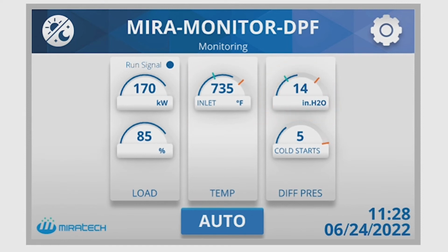You may have noticed a delay between when the parameter was outside the acceptable range and when the alarm was triggered. Those are fully customizable within the alarm set points menu to allow users to fine-tune exactly how fast they want the alarms to be reported. In some cases, you may want a long delay on low temperature, but a very short delay on high temperature.